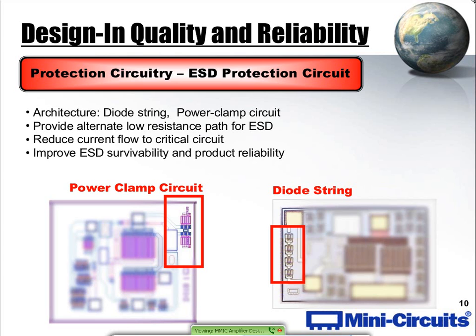We also get a little added benefit, which we believe is because of these PN junctions, particularly on the RF input. They have a very high survivability for input powers. What used to be a common limit of maybe plus 15 dBm for maximum input power survivability, we're now able to push over 100 milliwatts, even 200 milliwatts. And we think a lot of the benefits that we're getting out of the ESD diodes is enabling those higher power RF survivability.